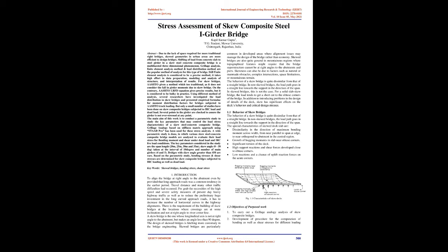Grillage analysis, finite element analysis method and load distribution method are the popular methods of analysis for this type of bridge. Still, finite element analysis is considered to be a precise method. It takes high effort in data preparation, modeling and analysis of structure, and interpretation of results. For skew bridges, AASHTO gives a method which is too traditional, as it does not consider the fall in girder moments due to skew. On the contrary, the AASHTO LRFD equation gives precise results, but it is considered to be bulky in practice.